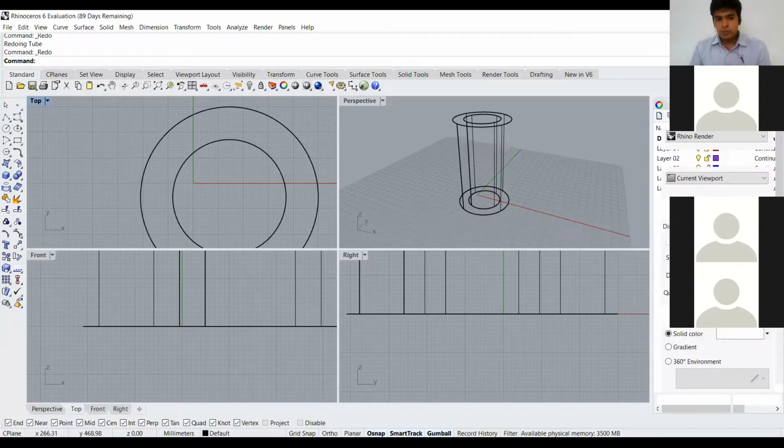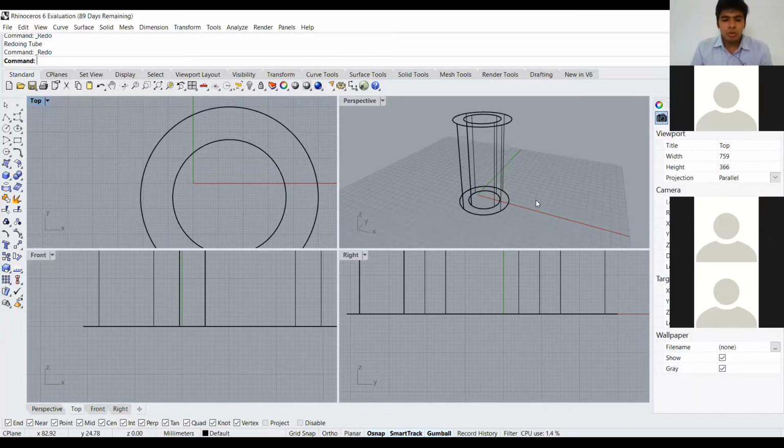There are two things that I'll say. One, keep the panels always on the right, because it's good to see while you're modeling. And second, always use Properties for checking your model, because sometimes the model gets damaged, or because of not modeling in the correct way, the model is not made properly. For example, once it happened to me that I was making a model for 3D printing, and they were just really simple steps, but I didn't follow them at that time. I didn't know, and I wasn't using Properties.